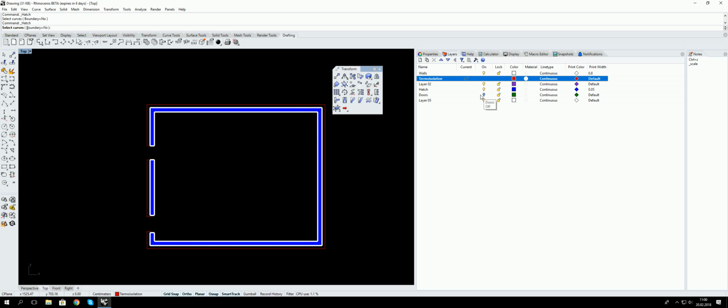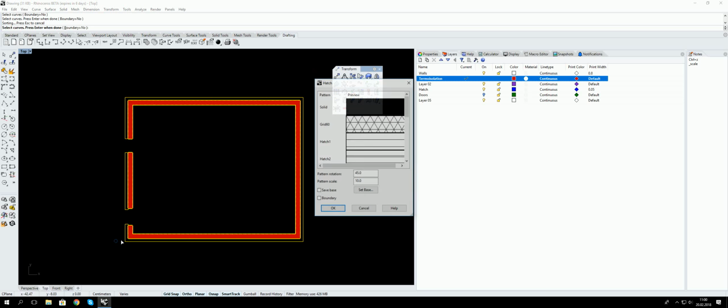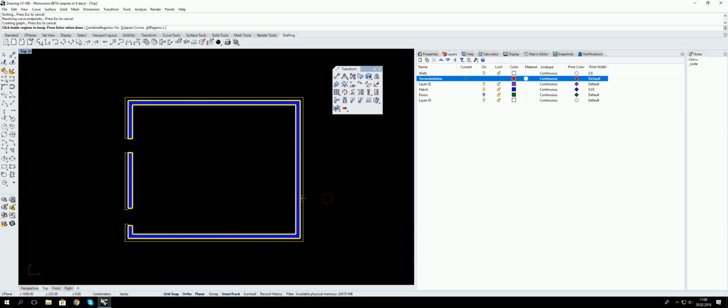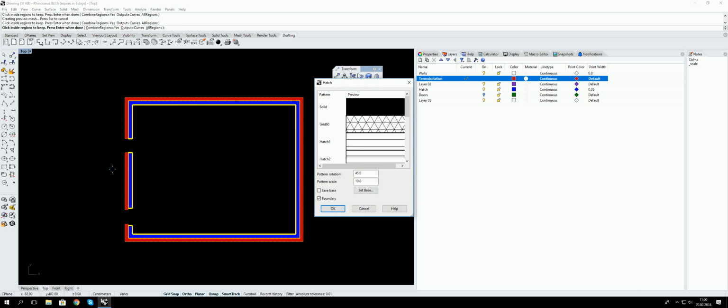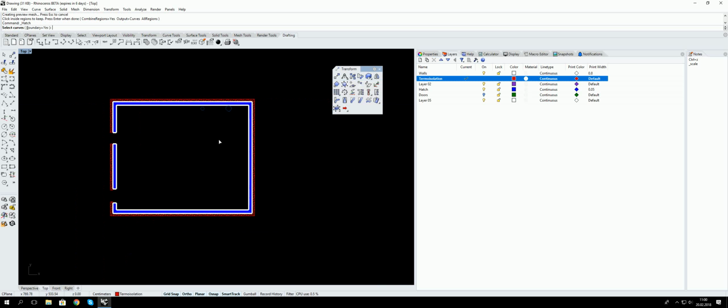and yes, and now the second way to make the hatch. Select all, boundary, pick in this place and in this place, and enter. This is the second solution. We need this grid. We should change the scale, and maybe we have a nice solution.